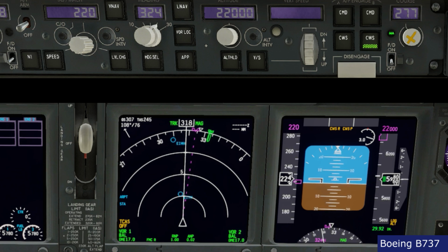and with the control with steering, I basically have a spare autopilot, so the autopilot is maintaining the pitch, maintaining the bank angle. The only difference is that I can change the selected pitch or the selected bank angle by applying a force on the primary flight control, so on the yoke.